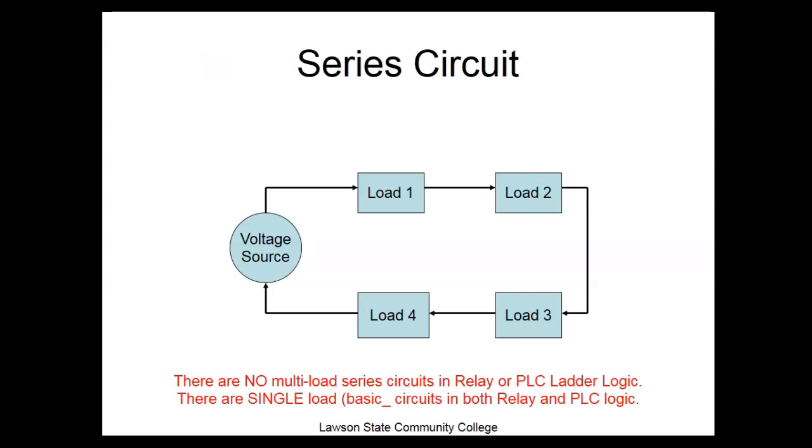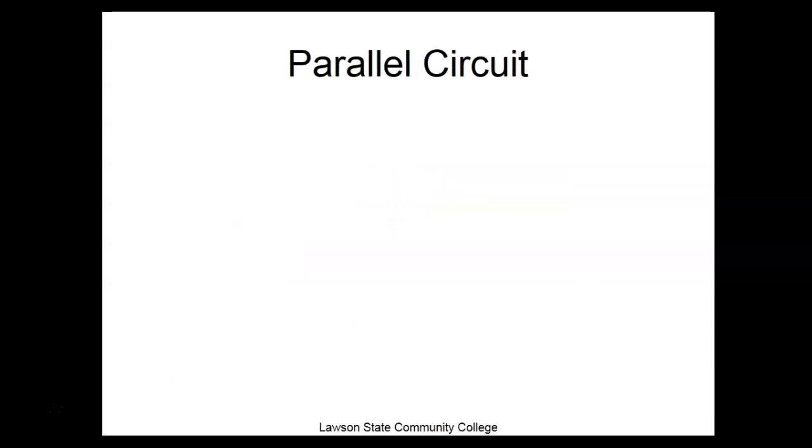Multi-load series circuits, we don't have these in PLCs, but this would look like this. This is similar. The problem we have with series circuits like this, if one of your loads go bad, then everything dies. So most people's got Christmas lights, and you notice one of the bulb goes out, and you'll lose a section, and that's because they're all hooked in series. So we don't run into these. You'll run into them a lot in electronics. So you'll learn how to do this when you take DC. You'll learn all the math and everything for it.